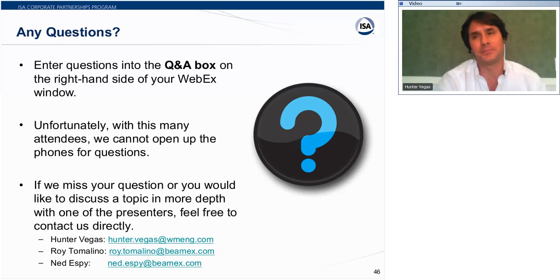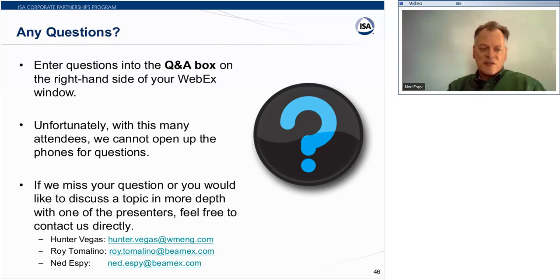You go first. No, I was just going to say that there's a lot going on in this area. Instead of running that capillary, you can run a cable from the transmitter up to really a second transmitter, and that's a very good way to do it. And then the smart transmitter at the base can do the mathematics to make a proper calculation.